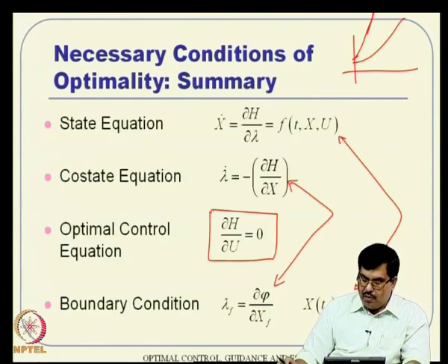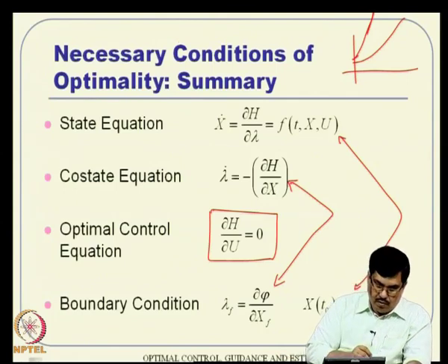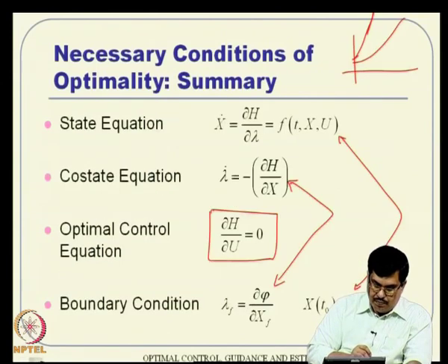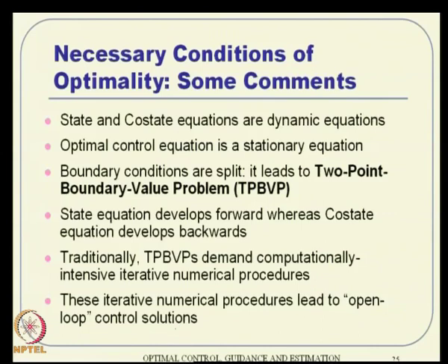Also remember, after all these difficulties, suppose you are able to solve it, ultimately you are solving it for a given initial condition only. That means we are actually solving an open loop control strategy. The control is not in closed loop sense. So, these are the difficulties of optimal control problem formulation in general. Problem formulation is nice, but you will end up with these computational difficulty issues.